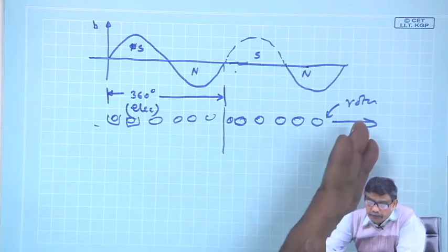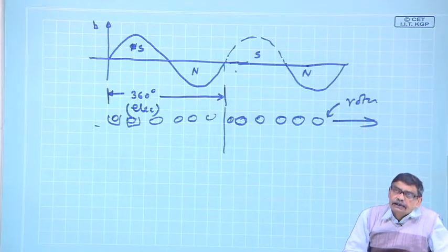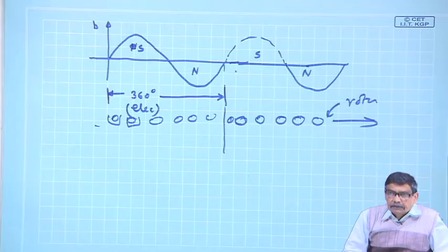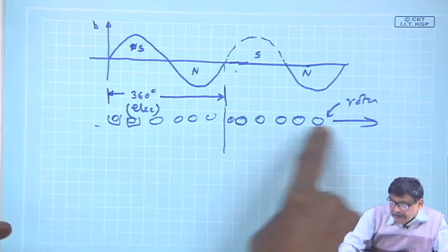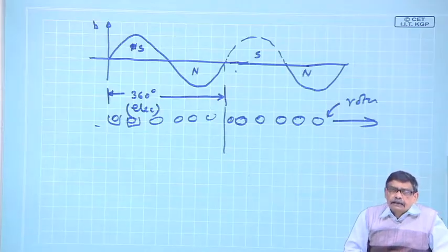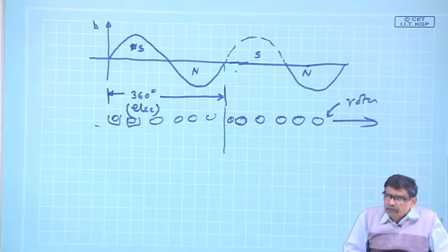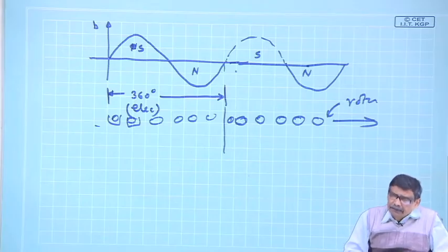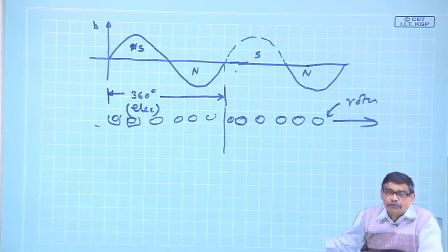If it is a 6-pole machine, next pair of poles under that, whoever is there at that time, same way it will behave. Therefore, what people do is this, although it could be a multipolar machine, they will always examine what is happening under a pair of poles, that is more important. If you know that, what is the point of repeating that?